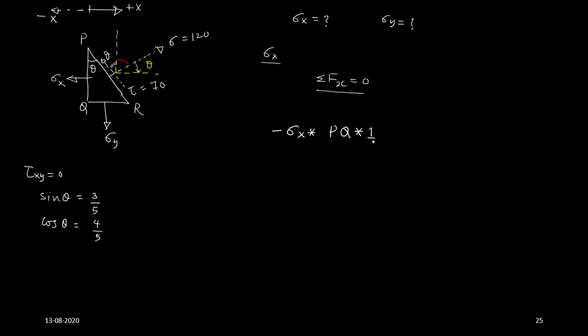It is the thickness of your stress element, because to get the force you have to multiply the stress term with the area. In the equilibrium equation you cannot keep the stress terms; the forces should balance.